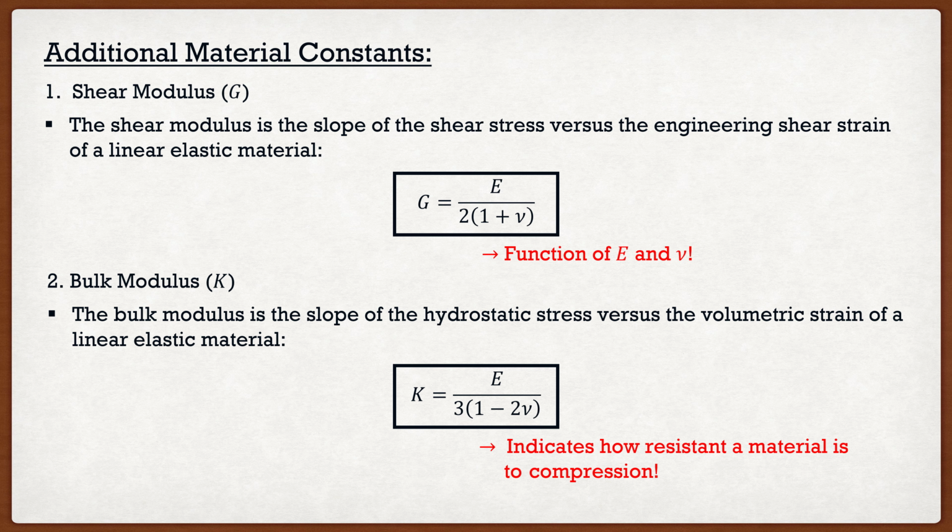However, once we get into modeling, we can create some nice assumptions or conditions to simplify it. So keep in mind that whether we're dealing with an orthotropic, transversely isotropic, or an isotropic material, at this point we still have that 6x6 compliance matrix. However, we can make some simplifications to narrow that matrix down from 6x6 to 3x3. The first one is called the plane stress condition.